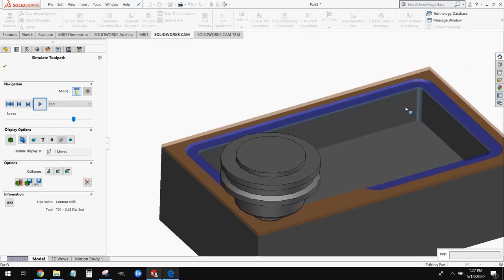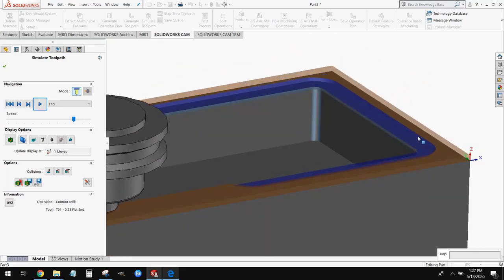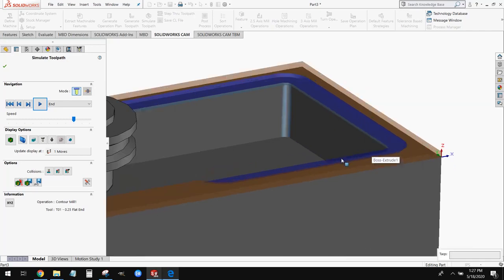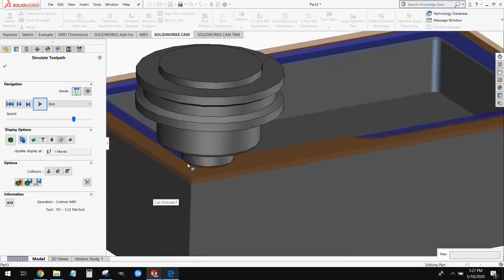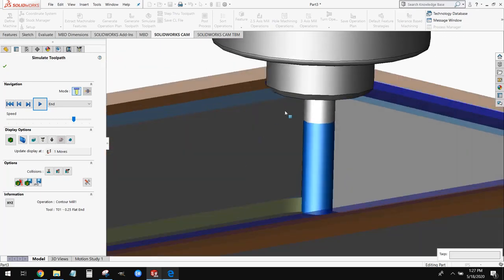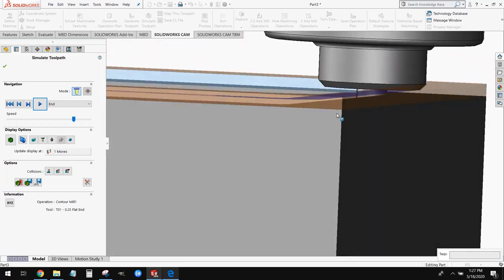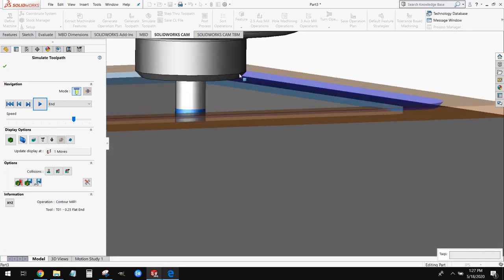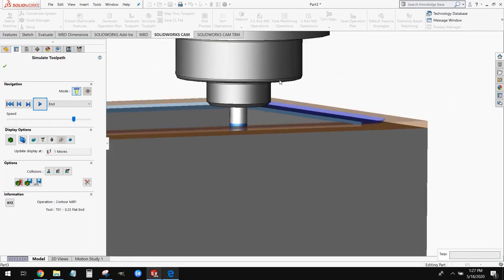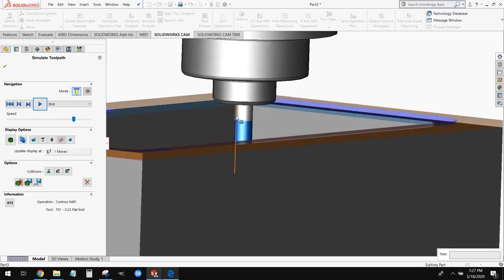And look what it's doing right here. See this right here? First glance, you think, oh, this is great. It's doing extra machining for us, right? This in engineering is what we call a bad day, because what's happening is the tool holder that 1/4 inch tool is sitting in is actually contacting this excess material that we have up here, right? Because we had to add 100 thousandths to this, that is actually interfering now with this tool holder. And this is going to essentially ruin our part for us. At the very least, it's going to damage our tooling.